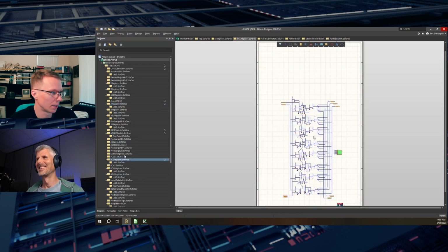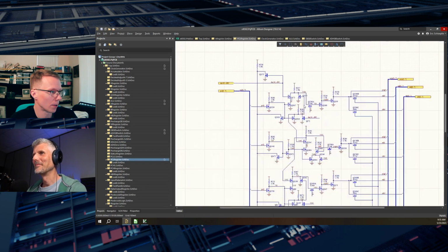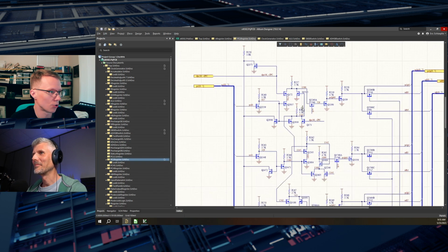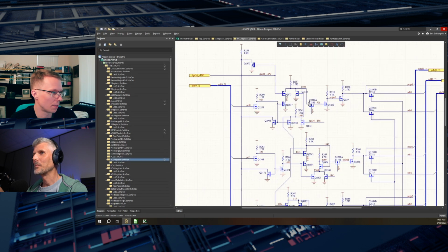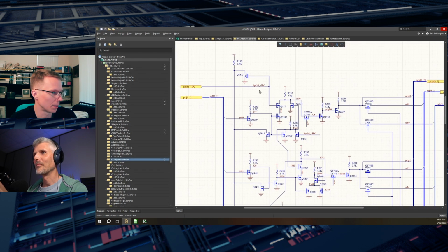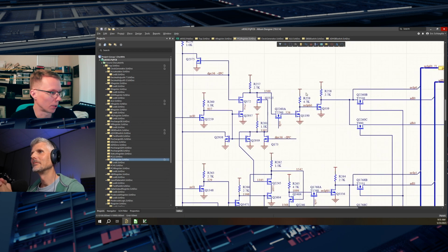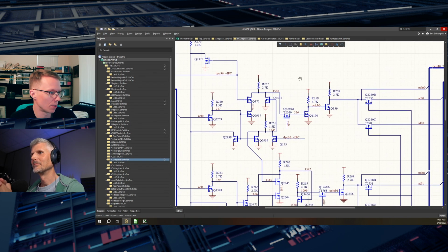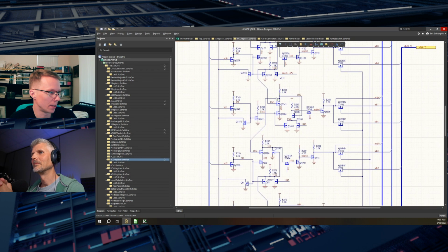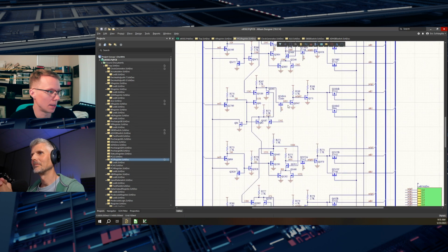Right, exactly. The program counter changes every cycle, so I think that might be a pretty good example of a dynamic gate. I'm just trying to think if there's one that might be more clear. This one's okay. So we're looking at the program counter. You can kind of see there are these diagonal lines going in between each bit. So that's how you propagate the carry.